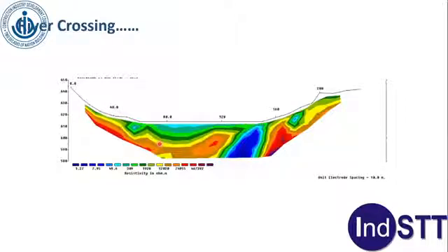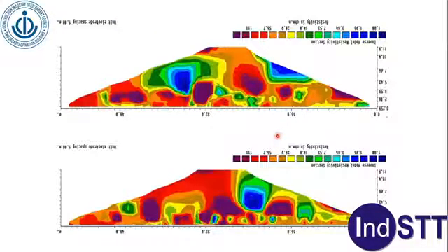For example, there is some seepage from this tunnel and you want to see where exactly the seepage is coming from. You can do it across this. This is a preparation by drilling holes to put the electrodes. And look at this beautiful example. So seepage was actually coming out from here in the tunnel roof. Generally, you will try to drill here and grout. This is a very good massive strata. No grout will go here. The bad zone was actually here and the seepage was taking this path. So this gives you eyes before you start the rehabilitation, showing where exactly your bad zone is.